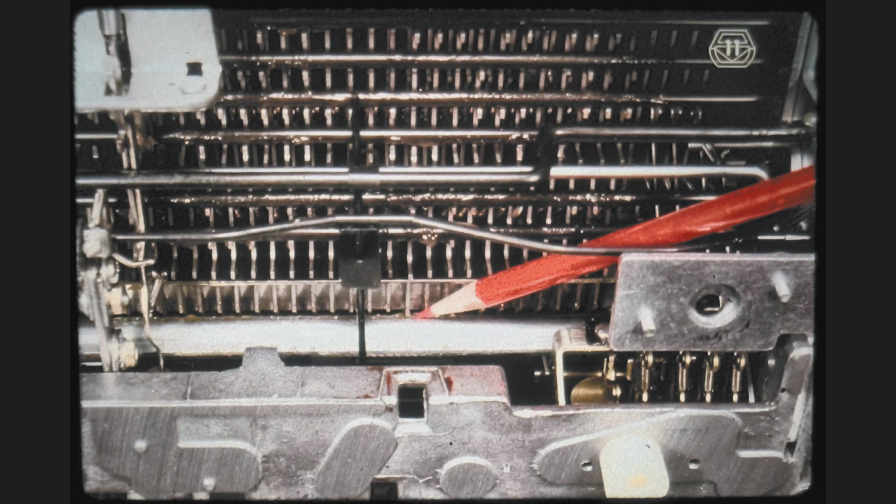If the filter shaft happens to be rotated too far top to the front, it can interfere with the depression of the interposer. If this happened in the field, the operator would probably call because of an occasionally very hard keyboard, or simply because of a plain locked keyboard. As you start working with the input section, it is necessary for you to be aware of all mechanisms which have the ability to lock the keyboard. This is just one of them.